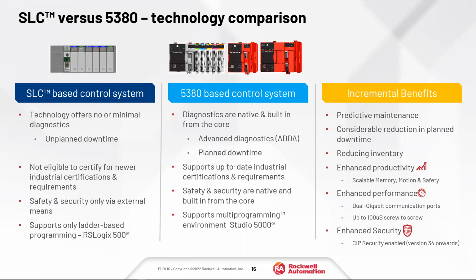The 5380 now has built-in security. It seems like every day we're talking to customers about securing their systems. If you have an SLC PLC, you're just not going to be able to add a whole lot of security to it. Maybe you can surround the product, but you're not going to be able to have built-in security like you can with a 5380 with built-in CIP security.